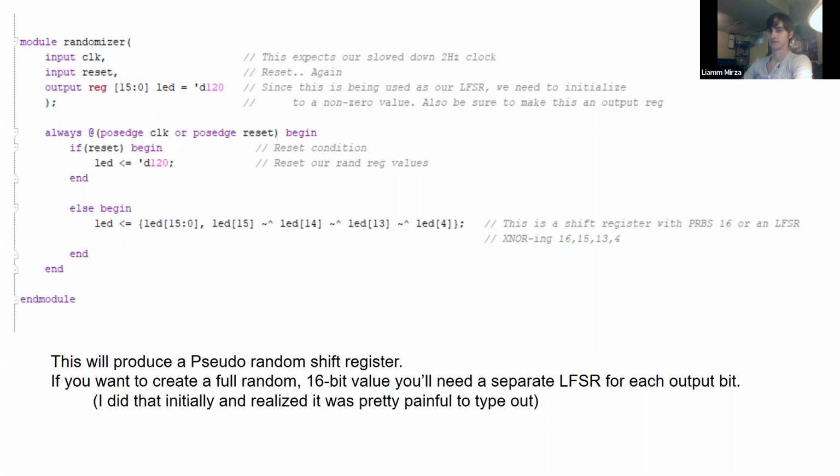That'd be a lot of flip-flops. You'd need 15 7-bit registers minimum, because PRBS 7 is a good one, it's enough randomness. There's 127 possibilities there. With what we have here, I think we have a bit more than 127. I think our sequence is quite large. But you'll notice it repeating. It's not forever.